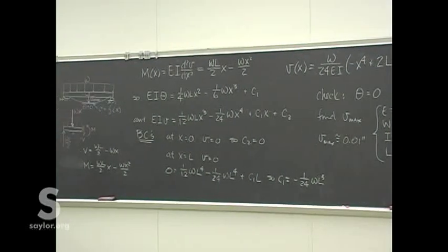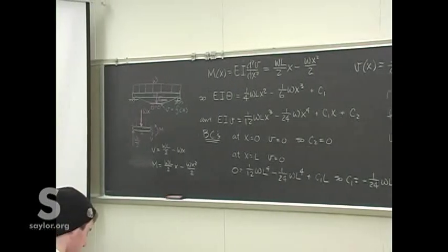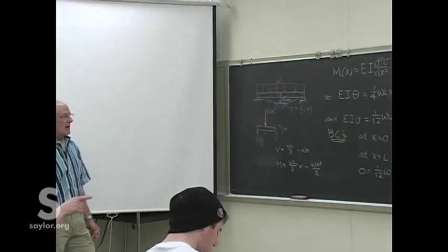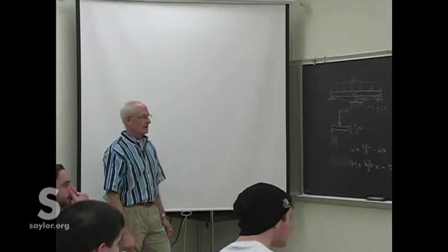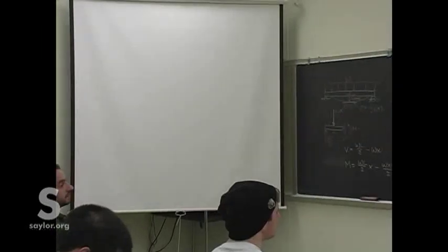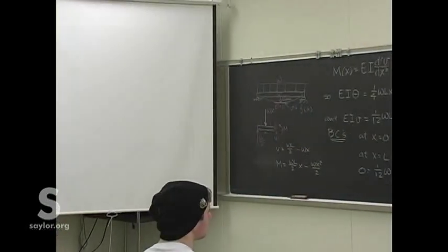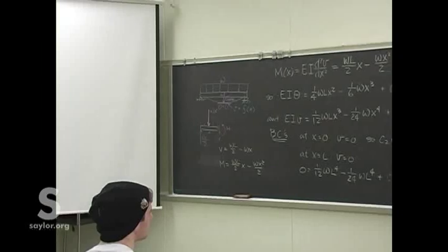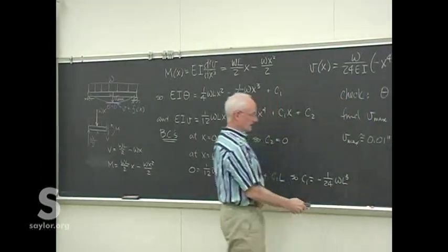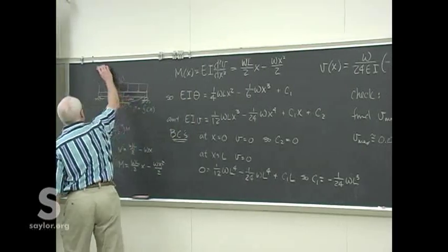Very, very small, which is good. You can put the beam up there. You don't want a big gap that you now have to compensate for as you build other things on top of it, especially if you do something 6 inches to the foot. Well, you had to make all the units work. This was 10 to the 3rd KSI. You probably want that in PSI, so it'll be 10 to the 6th PSI. Pounds per foot. The length in feet, you want all this stuff in inches.